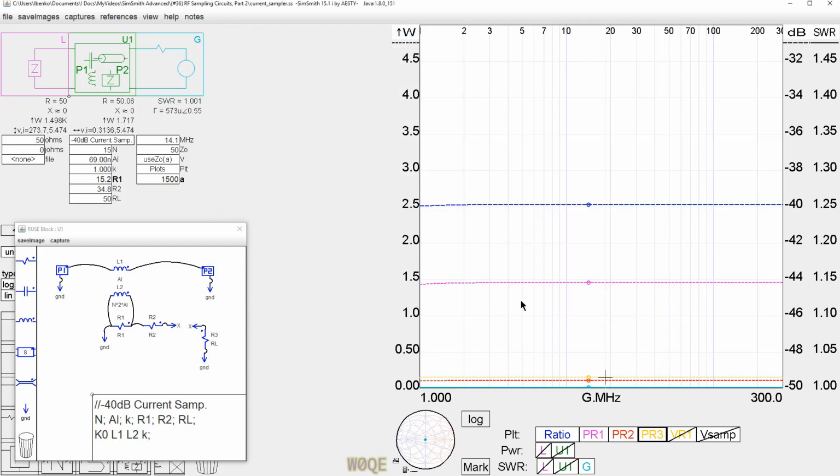And what we see is a little less than 1.5 watts in R1, which is across the transformer, and then R2 and R3 are down in the 1 or 2/10ths of a watt range. So this total power here is actually less than 2 watts. 2 watts is much, much better than the 29 watts and is perfectly acceptable to have in a small little box. We could also measure this power another way.